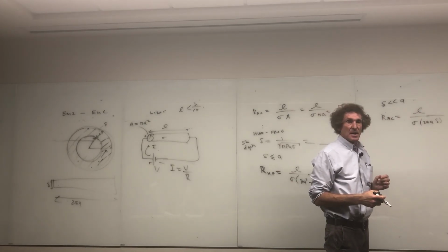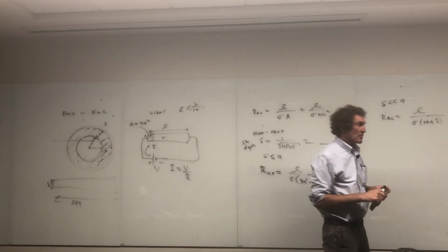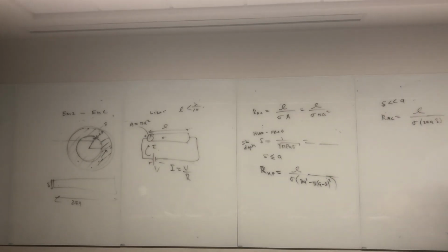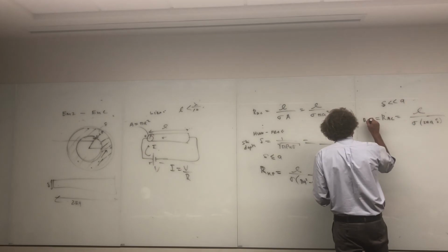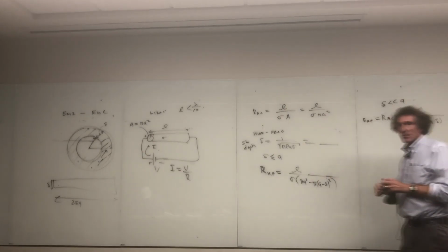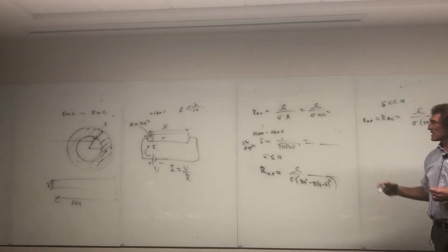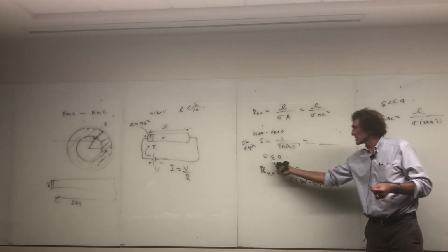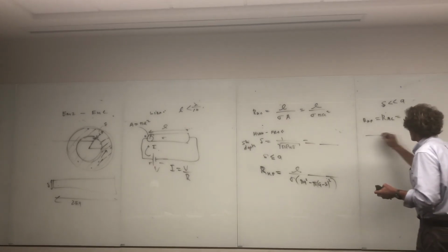Are you with me, class? These are straightforward calculations. We've actually done this before. Do you all recall? R_AC is R_HF, right? It's R high frequency. They're both the same. When I teach the EMC course, it's R high frequency. I think in Wentworth's book, it's R_AC. The key thing is knowing when you get there: it's when the skin depth is less than a.